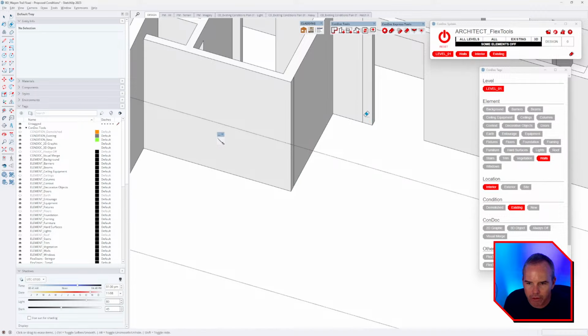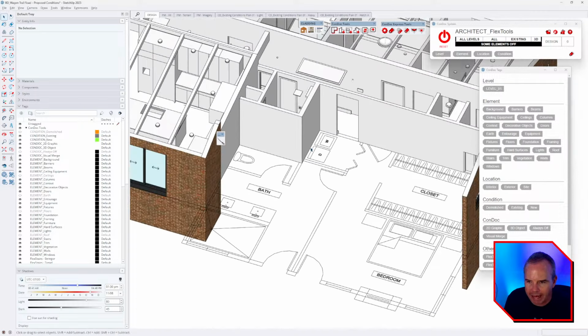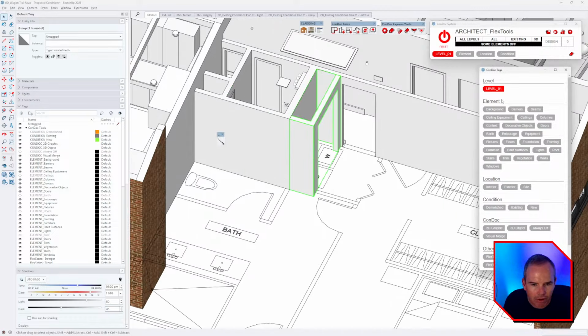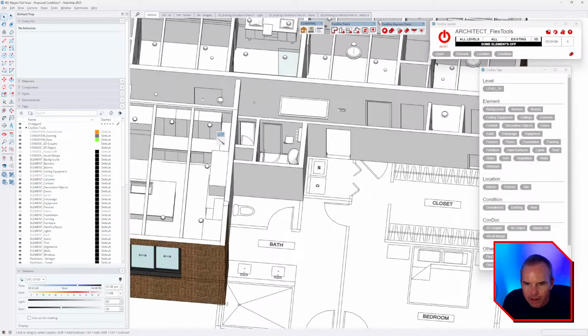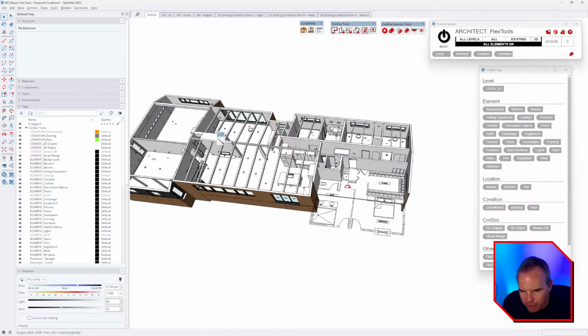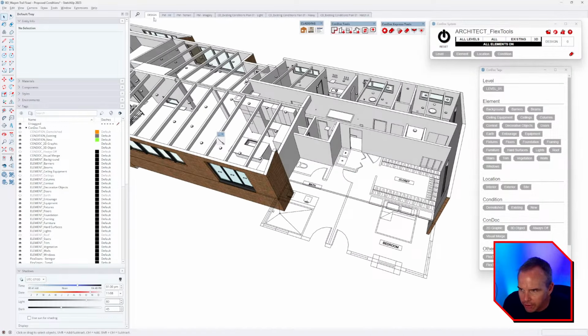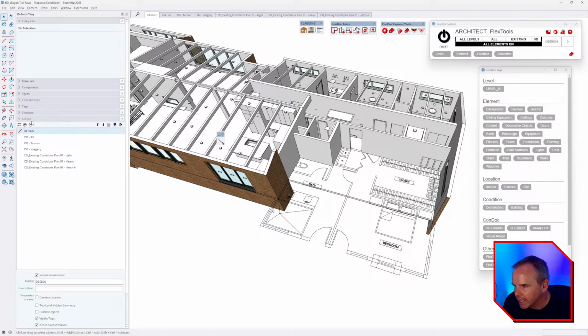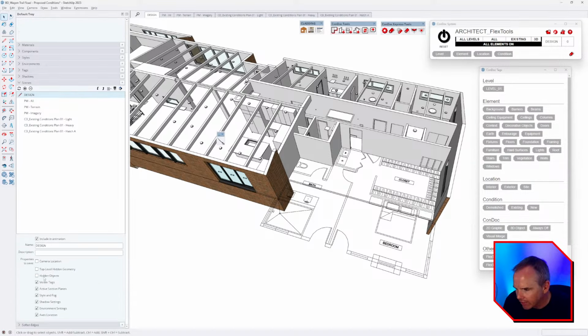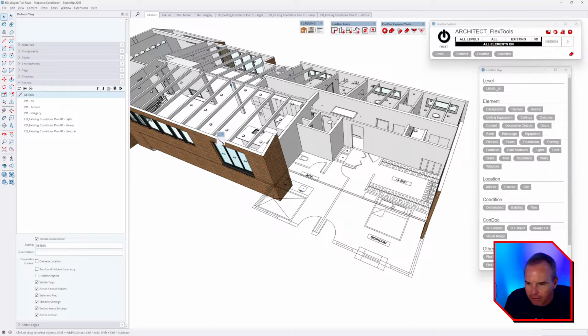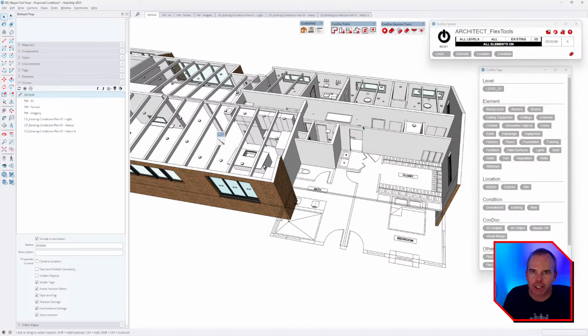And then I can use my eraser tool. And then I can back out of here, paste in place, level 1, walls, interior, demolished, like that. All right, and then you can always hit reset. Reset basically triggers that design scene. So whatever tags you've assigned, if you turn on the property to save visible tags, then you can trigger a specific layer state or tag state when you hit that reset button, which I like to do.